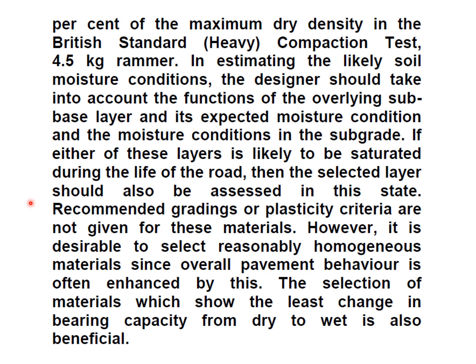Recommended gradings or plasticity criteria are not given for these materials. However, it is desirable to select reasonably homogeneous materials, since overall pavement behavior is often enhanced by this. The selection of material which shows the least change in bearing capacity from dry to wet is also beneficial. Thank you.